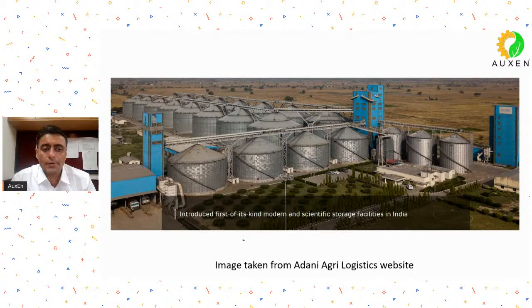So typically there will be a deck sheet that will act as the silo wall. Then you will have some vertical members, again cold rolled. Then you will have the top dome, again made out of cold rolled rafters, purlins, sheeting, etc. So this entire system that you see is made out of cold rolled sections. Okay, and then you store your grains. So instead of storing grains in gunny bags or open storage, you actually put them in the silos. Do you understand?